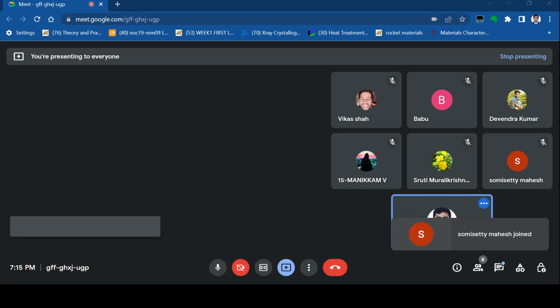So first here, 900 to 1000, Cp of liquid dT, 900 to 1000. Then minus delta H F. As I said, because we are going from liquid to solid, we have to reject the enthalpy of fusion, then only we can solidify that. So this is a minus sign.